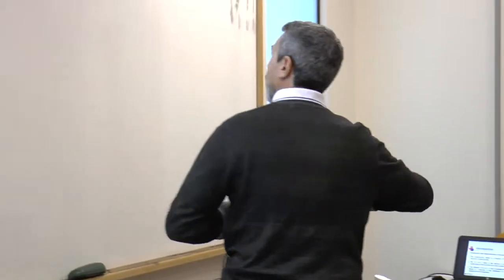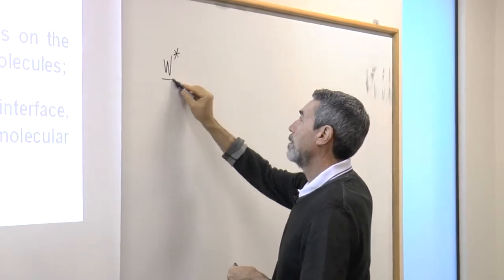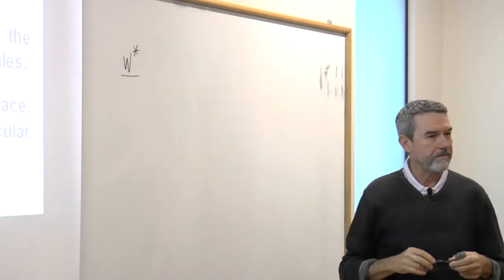One very interesting feature of crystal growth is that this is a spontaneous process. For crystal nucleation, the system has to overcome a thermodynamic barrier. If you recall my previous lectures, W star is the thermodynamic barrier for nucleation.